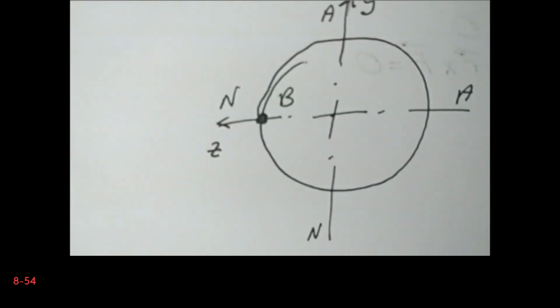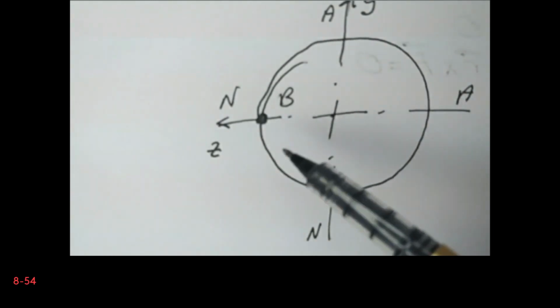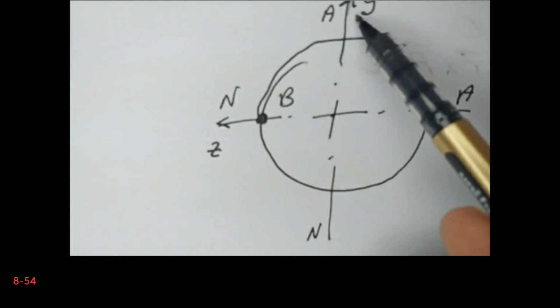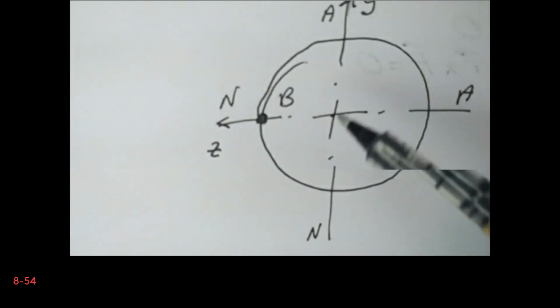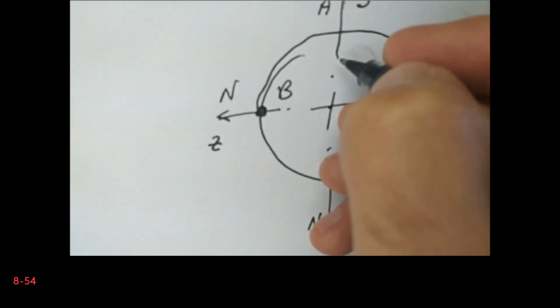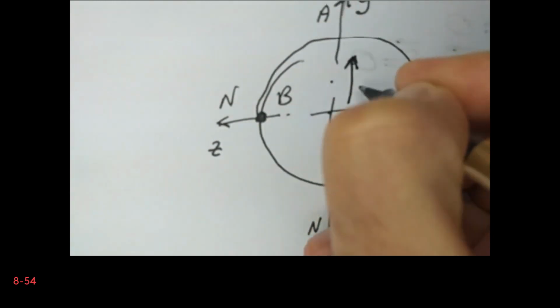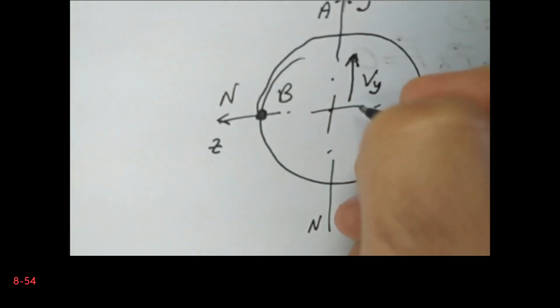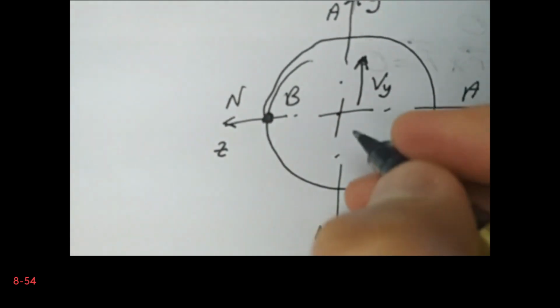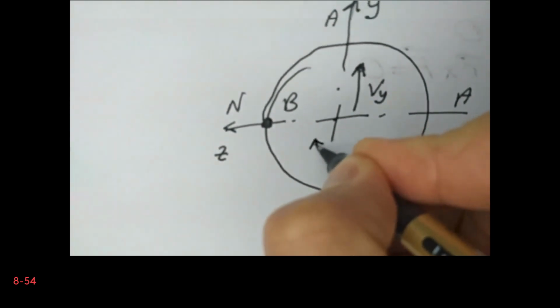So we have only two shear stresses. One is due to the torque and the other one is due to the shear force in the y direction. So let's calculate the shear forces. Vy is already given in this direction, so this is positive, like this. And we have the torque x, it is negative. So this means that the torque is clockwise.